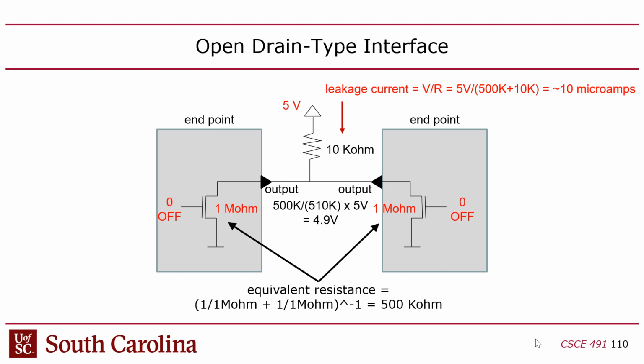This is just a contrived example, but in this case, I had 4.9 volts for a 1. So I had a 100 millivolt drop over this pull-up resistor. But again, it all depends on how everything is hooked up, right? Generally speaking, you want to have a relatively small drop over that pull-up resistor. And then if anyone pulls down, then you can set the bus to 0, right? When I say bus, I mean the wire, and when I say wire, I mean each of the 2 wires that are part of I2C. There's a clock and there's a data wire. So for each of those wires, the default value is 1, or someone can pull it down to 0.